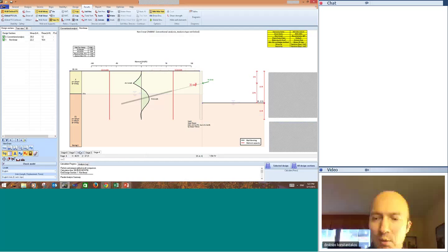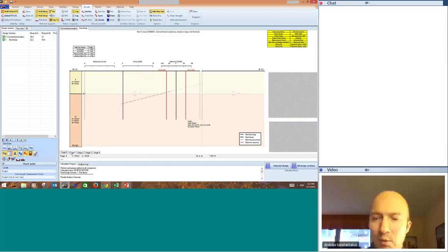The difference is that the nonlinear analysis automatically balances out all the moments towards the bottom of the wall, the shear, but we're also building up our displacements based on the previous states, on the pre-stress of the tieback. So we got here the cantilever displacements with the surcharges behind. We're putting the tieback pre-stress, the wall is moving back, we're excavating further, and this is how we complete our analysis.